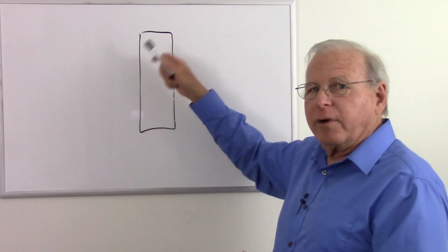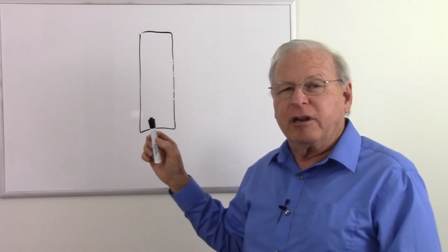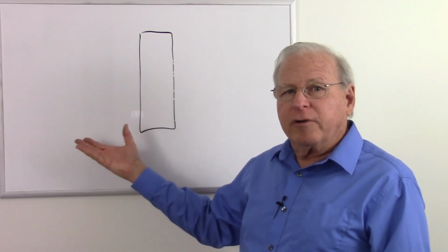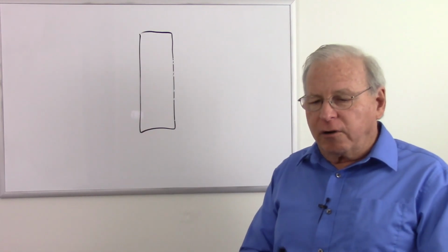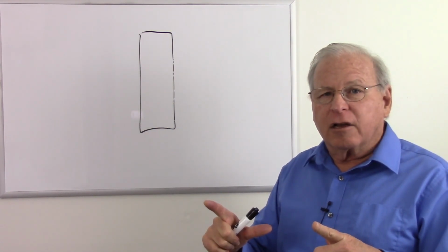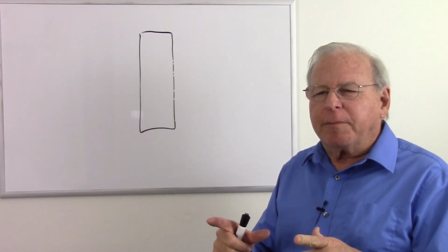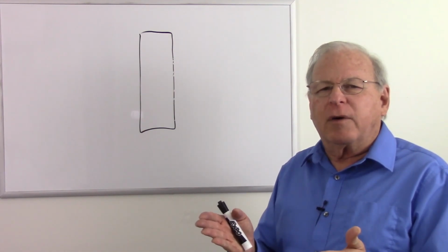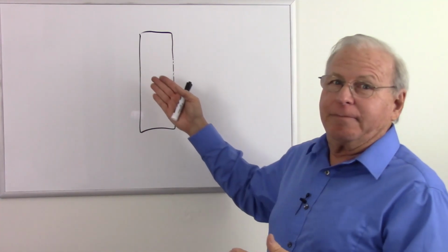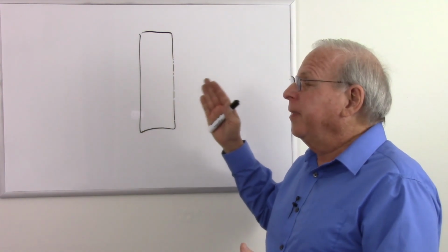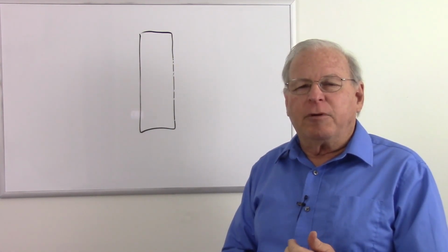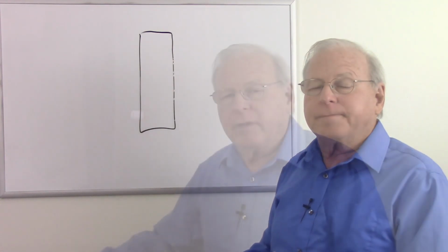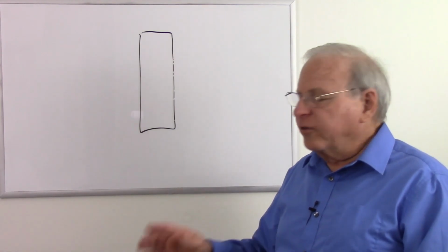The digital computer can do whatever we want, but the analog computers tend to be very fast. Another disadvantage of the analog computer is that it is designed to do one thing. Now, Derek showed a little square that he said was an analog computer. That was sort of programmable, but essentially by moving those wires around, you're rebuilding the circuit each time, and then it can only do that one thing. Where a digital computer, modern ones, can actually do multiple things at once. So, the advantage of the analog computer there is that it's fast. The advantage of the digital computer is that it's versatile. Now let's take another look at an analog system versus a digital system.